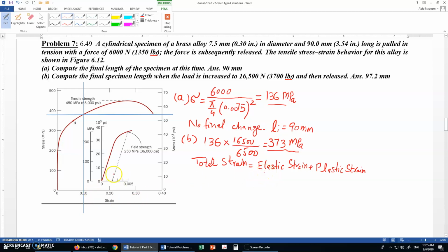The elastic strain is given by this figure over here. You can see that this is the stress strain curve in the elastic region, and a line from the yield strength has been drawn parallel to the initial slope of the line, and it intersects the strain axis at a value you can estimate as 0.002. Because this is 0.005, each line is about 0.001, so it is 0.002.